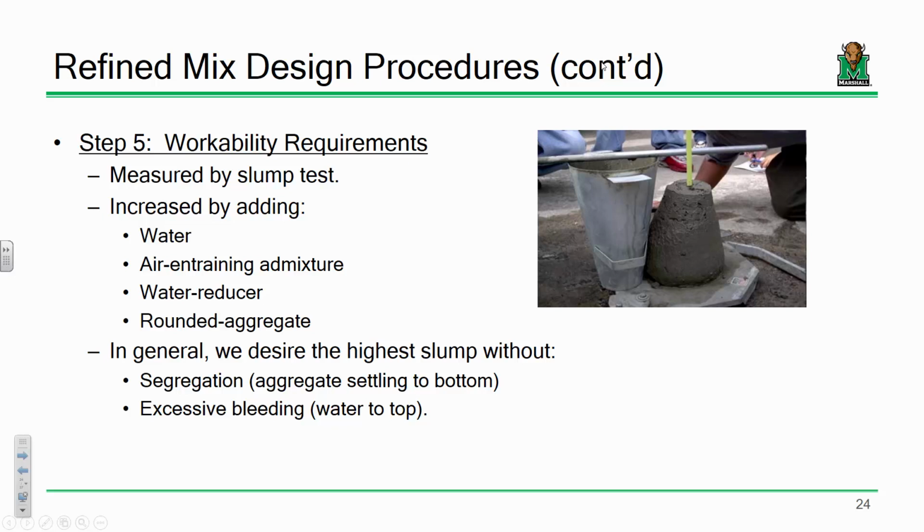Everybody's like, oh, well, you should have just added water at the job site. No. No. Once you do the mix design. But what we ended up finding is we had a mix that was fairly stiff, and our slump was actually pretty low, and so that's something that we can correct down the line.